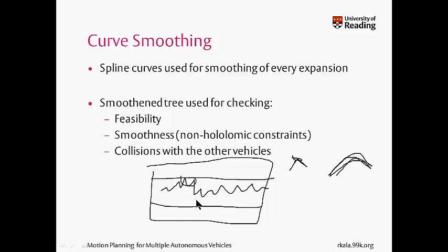One way of saying it would be very simple: let this be the path to be tracked by the vehicle. The controller can only generate smooth paths, so it will generate the closest trajectory. But even if this trajectory was obstacle free, it cannot be ascertained that the smoothed version of it, which the controller actually tracks, will be obstacle free.